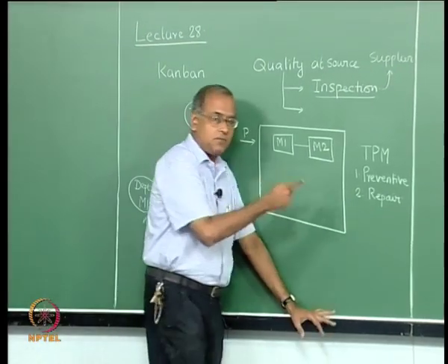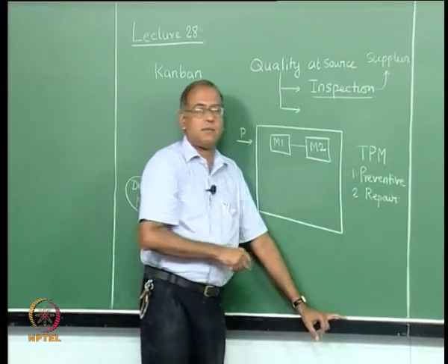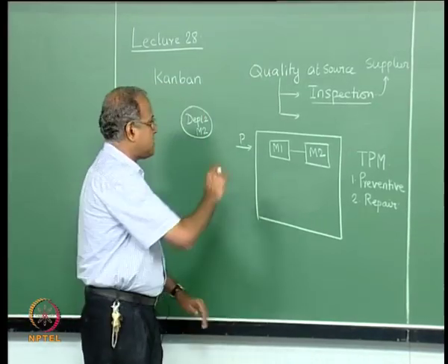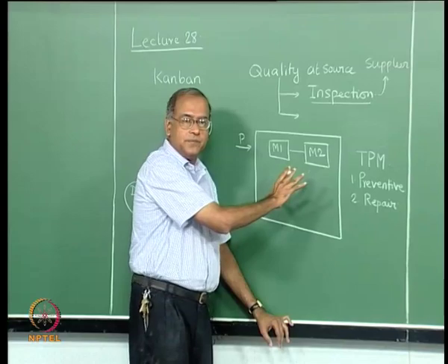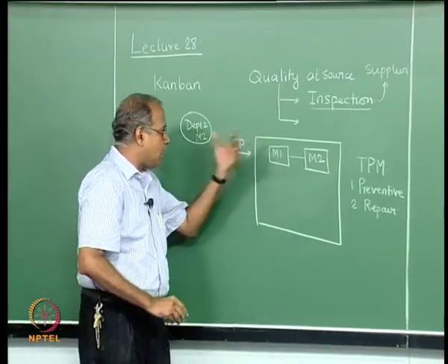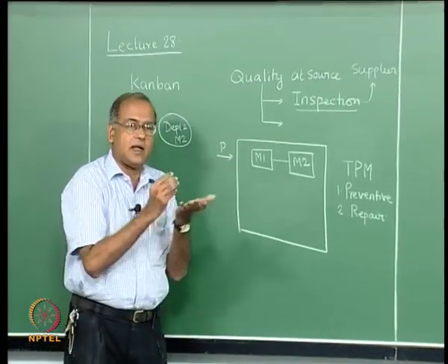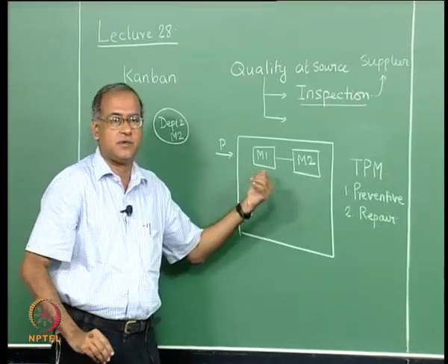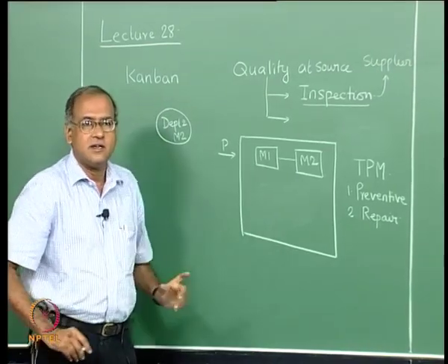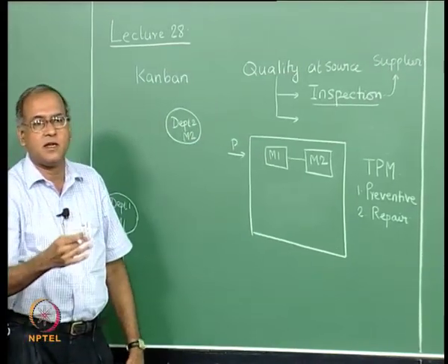If the emphasis on preventive maintenance is high, then the need for repair maintenance will be low, because the machine would work well. So, the emphasis on preventive maintenance will be very high, and a part of the preventive maintenance responsibility will also be with the operators. This would help increase the availability of the machine, and would prevent the operation from being unable to be carried out because the machine is not available.